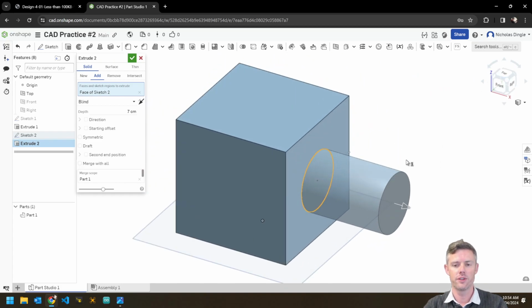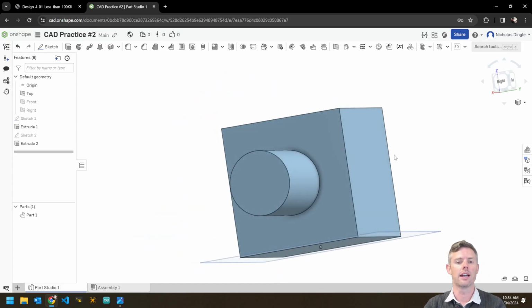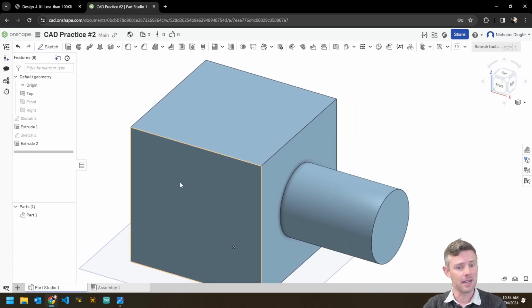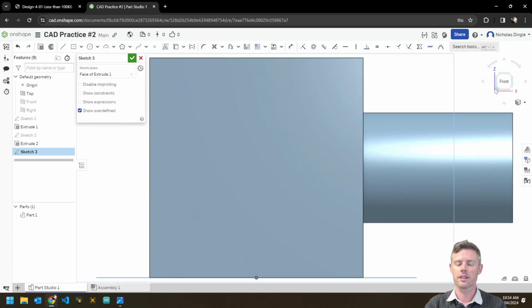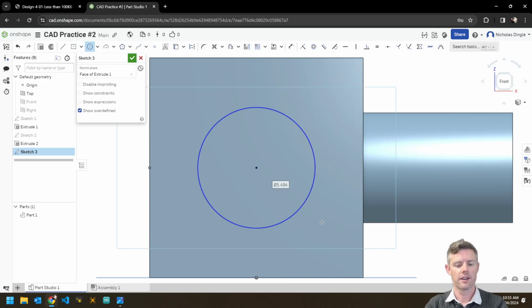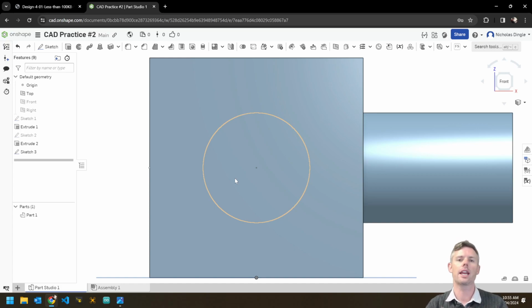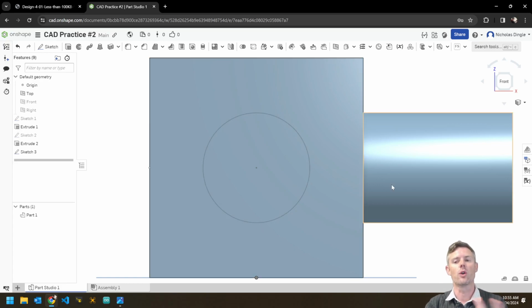Let's quickly go back to this view. Let's hit tick, and look at that. We've extruded our shape. He's looking beautiful. Okay, now, next step, let's cut that hole out. Okay, sketch, face, front, and then we're going to choose that circle again, find the center, middle, click, click, 5, enter, tick. Okay, it's as simple as that. You're going to get into this habit of sketching, setting your dimensions, making sure it's all black or gray, that it's all constrained, and then we perform our operation.